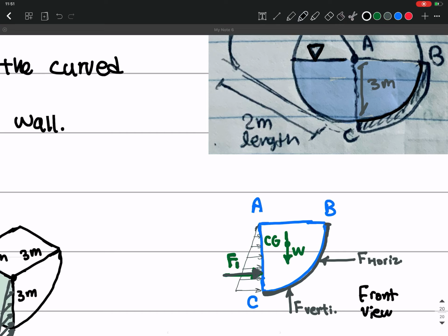So, this is how I draw the free body diagram because it's easier, but you can imagine the real one, if you just want to draw it for this element, the free body diagram is going to look something like this, right? Here we have pressure by the water, which is going to be rho g h, where h is 3 meters. And then here we have 0 because it's the surface, so we are going to have something like this, right,